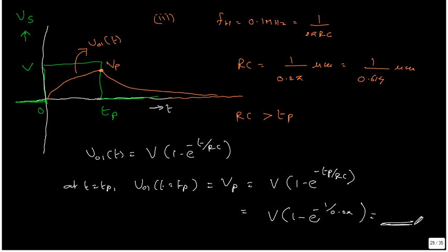So from this question, you can draw the expected waveform by comparing the pulse width with the circuit time constant. Once after comparing, you can easily get the relation. From that relation, we can ensure whether the capacitor reaches the final value or not. Accordingly, you have to draw the expected waveform.